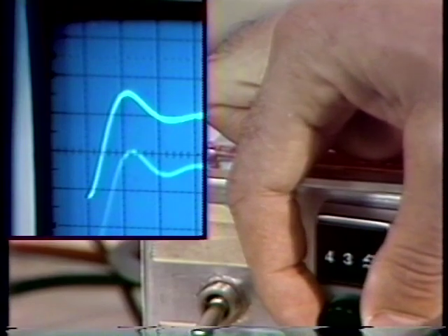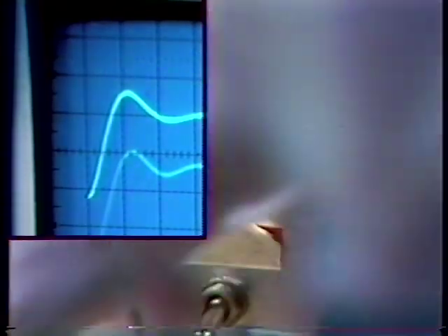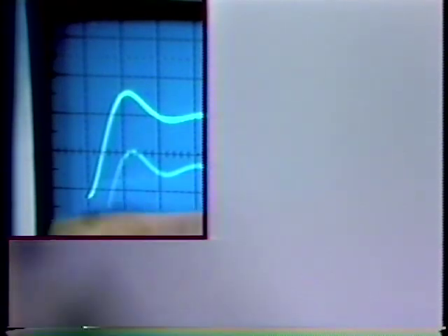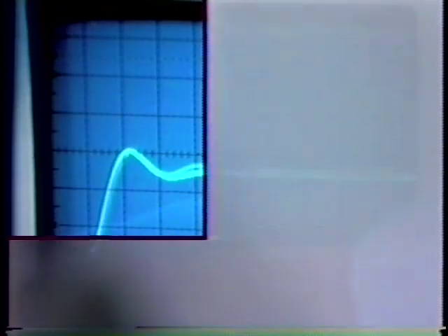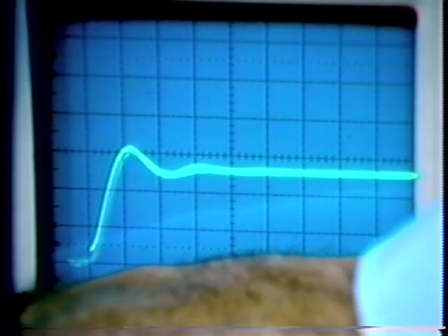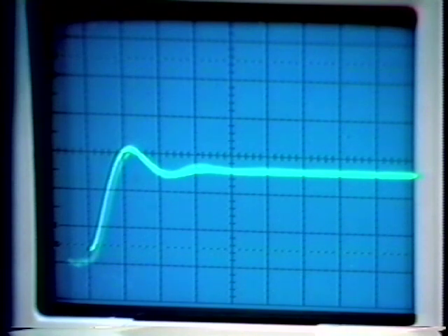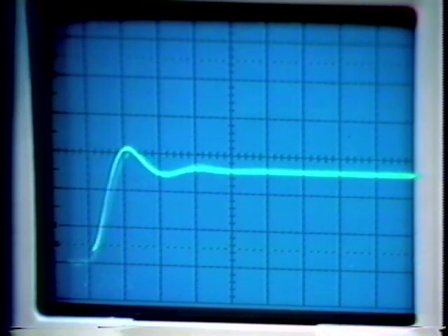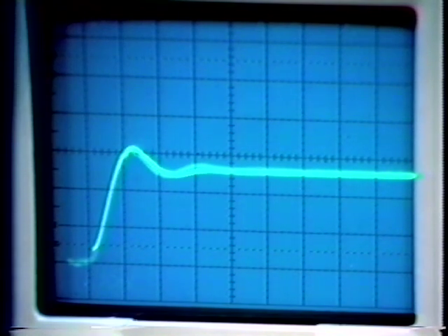And I don't know, there we're at 0.43 or something like that for a damping ratio. And now let's see how well we're matching. Well, we're not quite there. There are a number of degrees of freedom as far as how we line up the various traces. We can change the time scale by simply changing the time on the oscilloscope. That really corresponds to modifying omega n, or the picture changes as though we were modifying omega n.